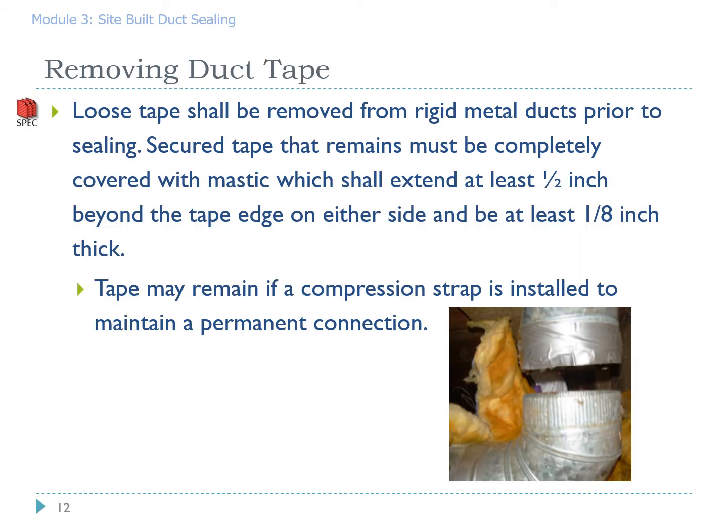As this picture clearly shows, duct tape alone cannot fix ductwork. Ductwork has obviously failed, and the duct sections have decoupled from each other. Yes, they didn't put screws in. That was their first mistake. Mastic is intended to stick to the sheet metal. Mastic is not intended to stick to the duct tape. The duct tape adhesive will come loose eventually. When that comes loose, so will the mastic.